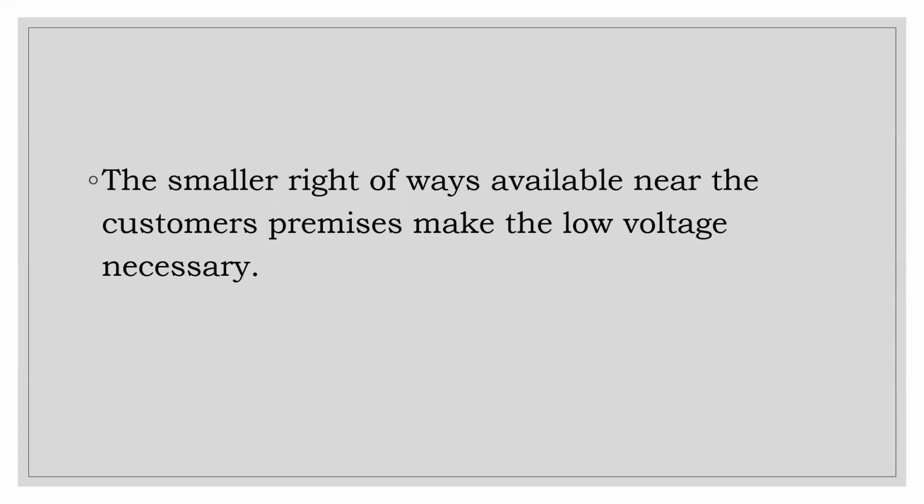But within a residential community, what is on the pole is 24 kilovolts, and we are good with that. Of course, you can have your spurs, which are your 3-phase 415s going down a little lane. You're not going to carry the 24 down that little lane just for those few houses. Okay.